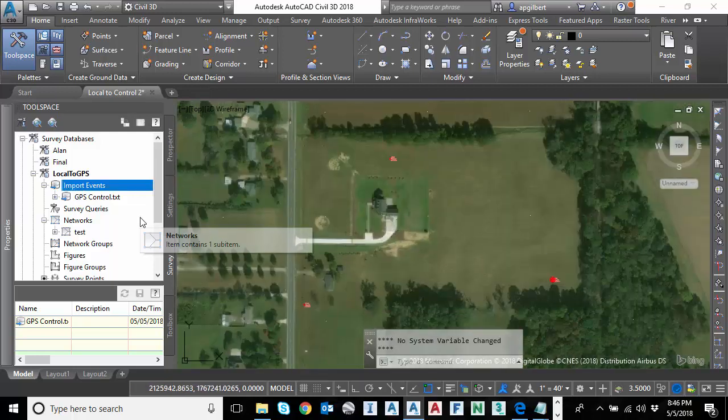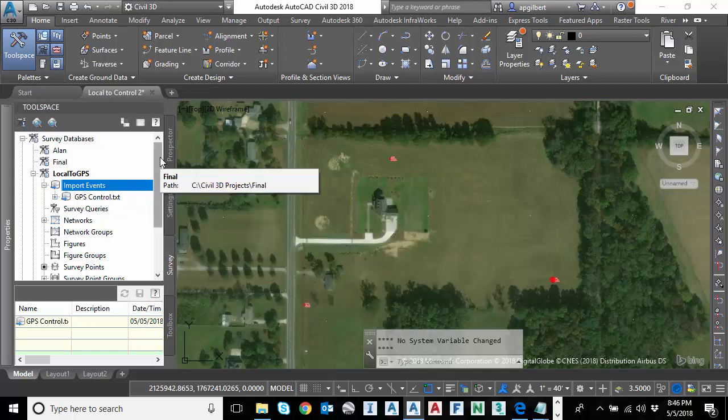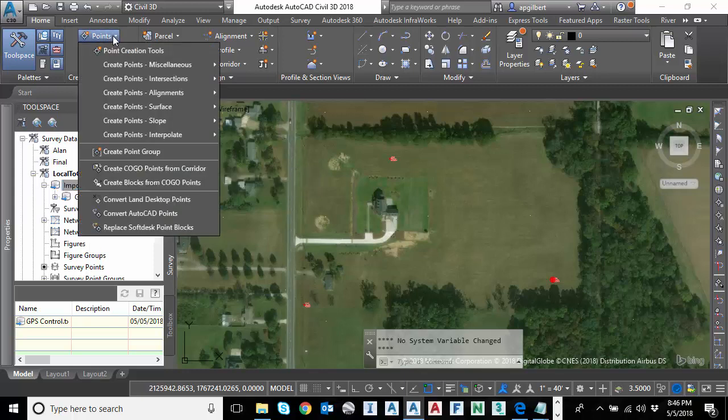So there's quite a few ways to do this, just like always. You hear me say that a lot in Civil 3D. But let's talk about just a few methods. I could import those fixed points from the local survey, from the total station survey, into here. I could unlock those coordinates, which are just COGO points in the file. I could move those and then bring them back into the survey database in a couple ways. But since I'm heading towards a COGO workflow anyway, I'm not even going to bring it in here first to confuse the issue. So what I'm going to do is jump to the points import, my regular COGO. So we're going to use the COGO tools just to translate and rectify these up into coordinate space. Then we're going to either export or add those straight to the survey database.